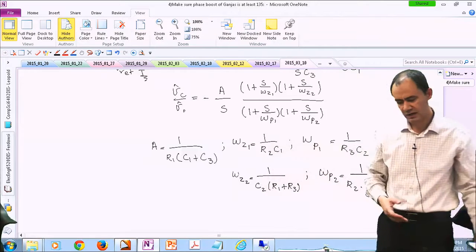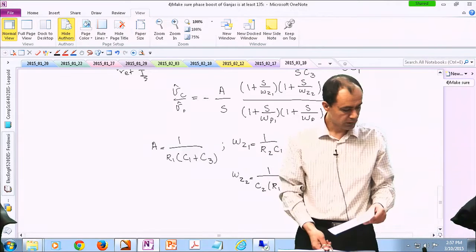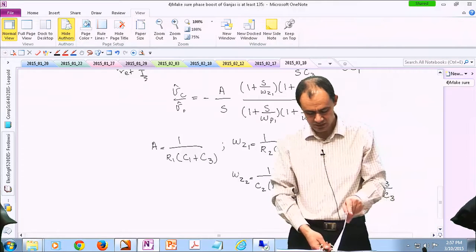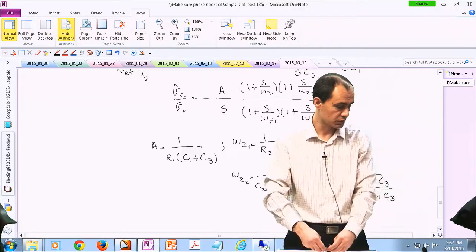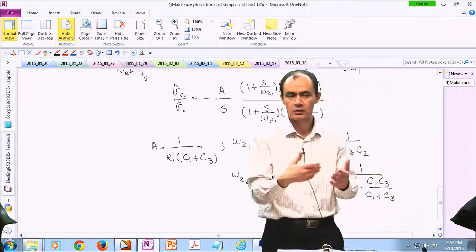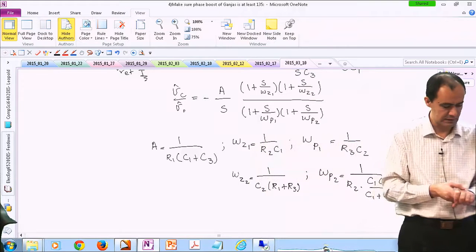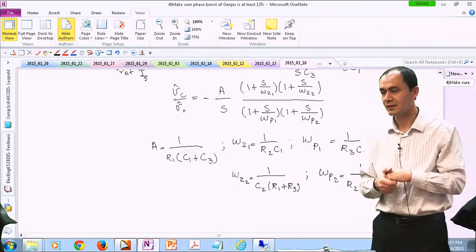And now as you can see, you have extra degrees of freedom. It's not like if you know where your omega P1 is, for instance, 600,000, that exactly determines what R3 and C2 should be. So you can select a few of these numbers, using the components that you have in the lab, like a film capacitor, then find a numerical value for the other components.